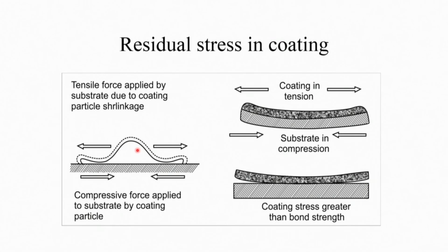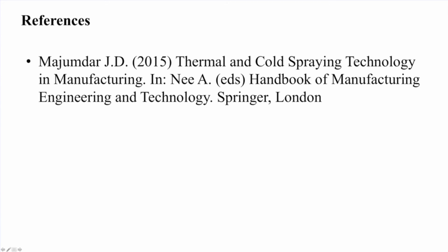You also have to be careful to reduce the different kinds of defects introduced by the thermal spray deposition process, particularly defects like porosities, blowholes, and inclusion particles. If it is a reactive material, you can also carry out thermal spray deposition in a closed chamber, where you get rid of all atmospheric contaminants. Process parameter selection is very important, and depending on the material you choose the proper technique, so that you get proper adherence at the interface, with proper surface finish and good quality coating on the substrate of your choice for the desired application.